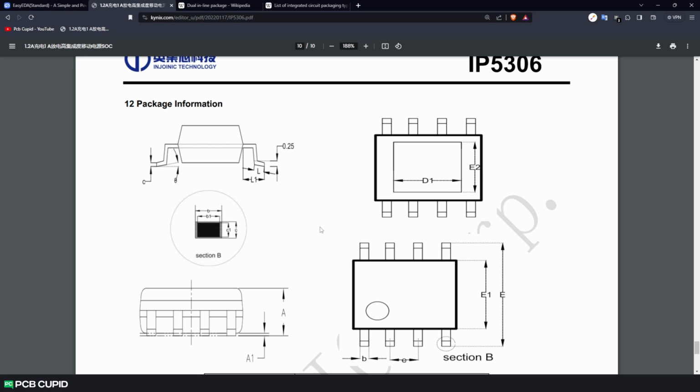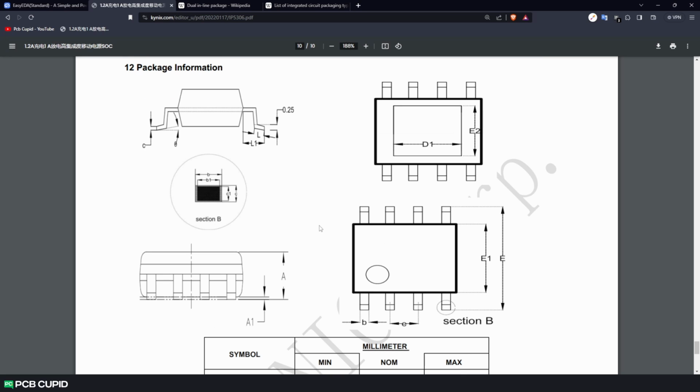Not all the datasheets provide the dimension for the footprint. So we have to slightly modify this dimension to make a good footprint that has enough space to solder as well as place the component. I know there's a lot of information on the datasheet, but we only need to focus on a few details to build a footprint. As a starting point, we can always start with building a pad, where the components will be soldered, and then build the rest of the footprint.